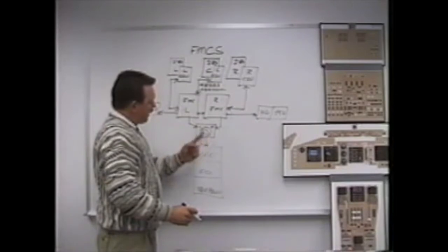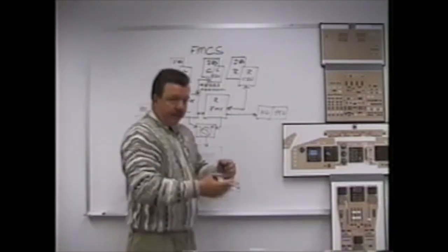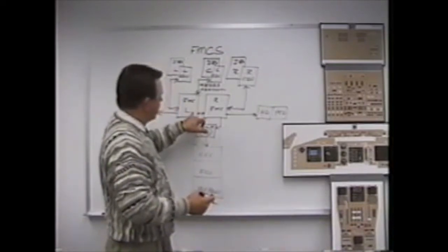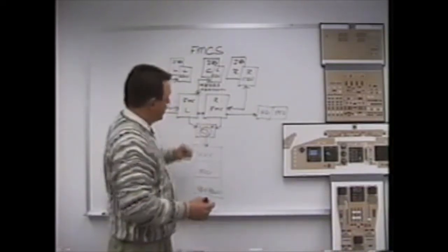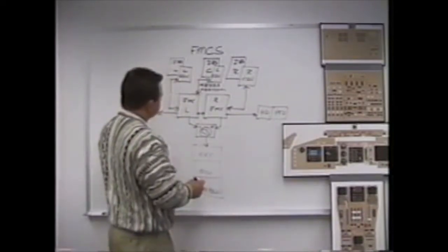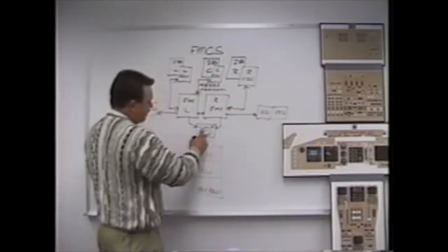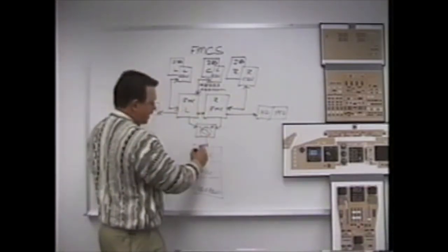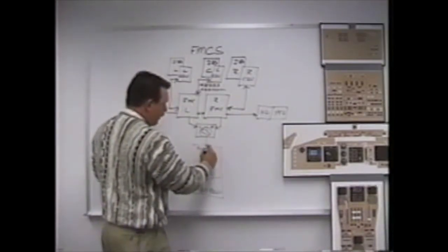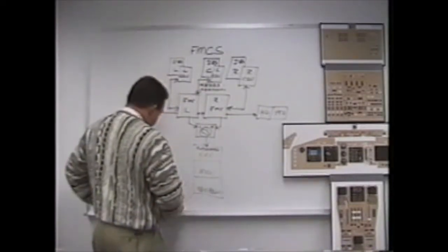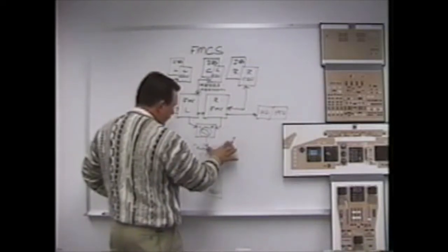The reason for the left FMC and not alternating between left and right like we do on every other thing is because the left FMC has the backup power source. The right FMC does not have a backup power source. Specifically, electronic engine controls, what they're getting as their signal from the FMC is the auto throttle function. What power to set, when to throttle back, when to push up climb power. I meant auto throttles.